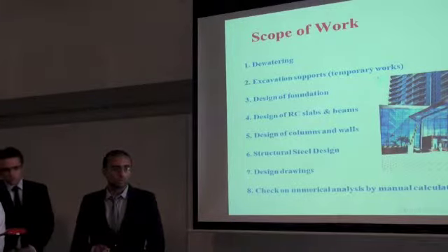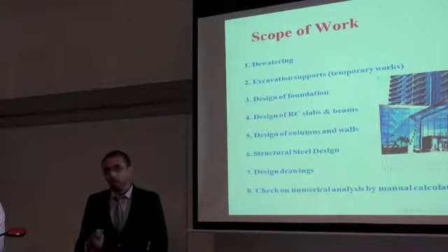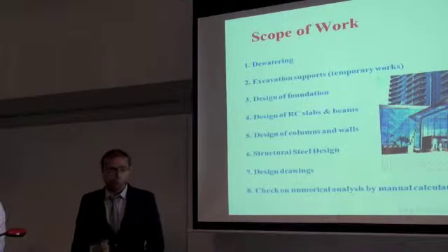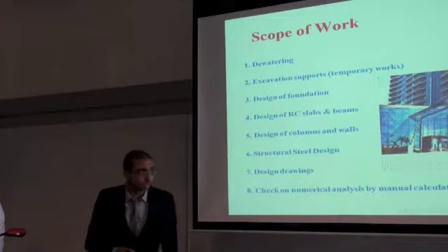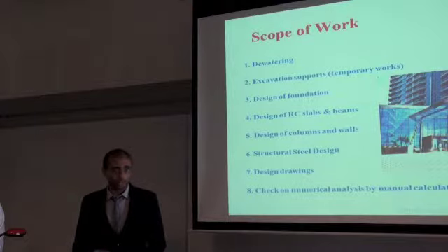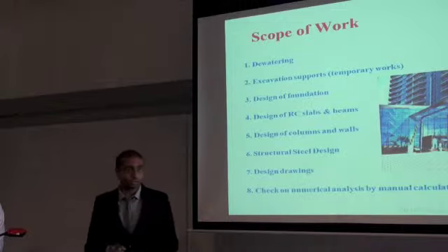First, we have to deal with the dewatering, since our project is directly adjacent to the Nile. We'll decide on an effective and suitable dewatering system for the structure. Moving on to the excavation supports, which are basically temporary works for excavation, we'll do the arrangement and design of diaphragm walls, the arrangement and design of piles, and also the arrangement and design of waler beams.